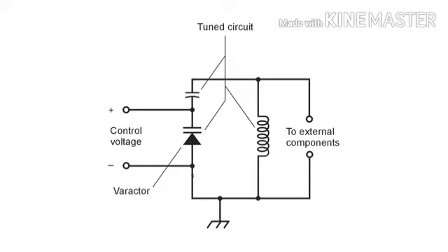But you can create a tuned circuit in your ham radio, for example in a transmatch or a radio amplifier or oscillator, using a varactor diode along with a conventional diode and an inductor arranged in a fashion such as is shown here.